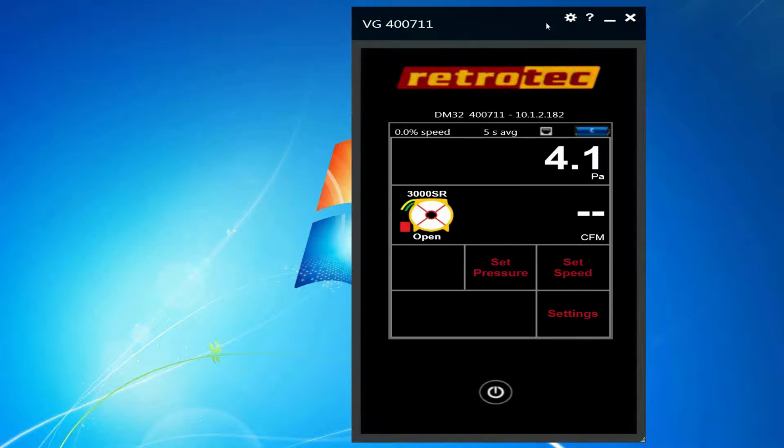You don't even have to get the gauge to control the fan, and all of our fans have speed controls on them. You disconnect the speed control cable, which is an Ethernet style cable. It doesn't plug into the Ethernet, but it's an Ethernet style cable. You turn it to 0 to reset itself, then you turn it up, and you can get the fan to operate. So that's the simplest way to do it, and then just look at the gauge and see what readings you get.